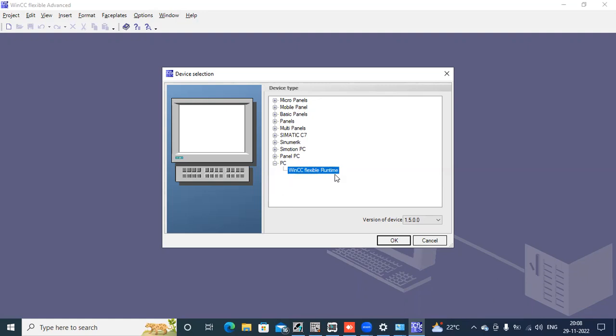And in TIA Portal, the updated software version, they have launched new panels called KTP panels. The similar numbers like 170, 270 like that. Same conversion, you have to do with similar properties in the file. The only thing you have to do is conversion in hardware.